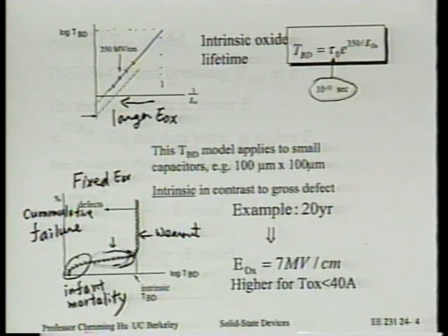No, it won't. The reason is the rest of the capacitor has already used up some of its lifetime during your first experiment. In fact, the whole point about intrinsic breakdown is that suppose the first breakdown is intrinsic. Then if you chop that off and apply the voltage again, it will not take long for another spot to break down because we're getting close to intrinsic now.